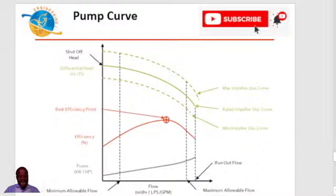If you look critically at the pump curve, the flow increases from 0, say in the range of 10 cubic meters per hour, 10, 20, 30, 40, 50. It increases as you move from the left side towards the right end. Now look at your head. From 0, your head increases towards the vertical axis.